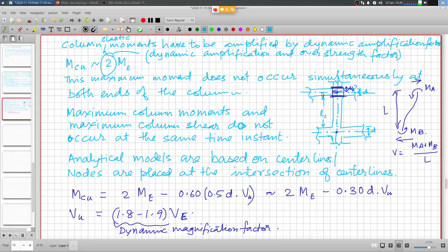In this case flexural reinforcement has to be provided according to these moment capacities and for this maximum shear. And as I said, in case the axial load is very small, we accommodate all the shear force in the beams up to that level coming from the top, and add all of that, and that provides the axial force due to earthquake effects.